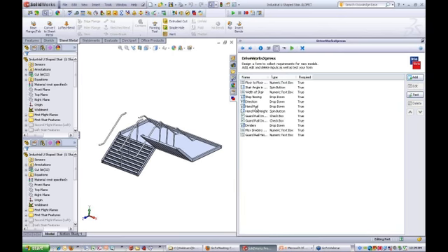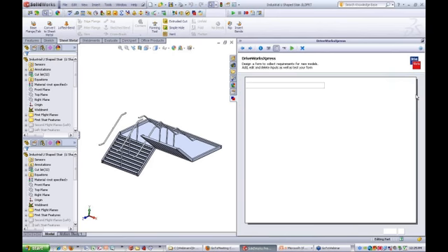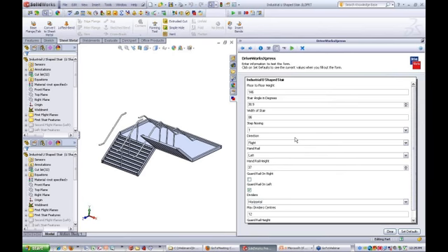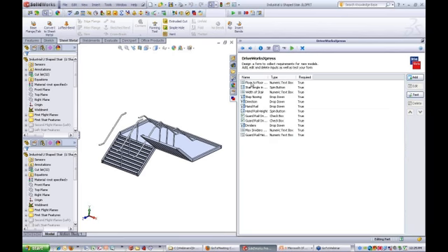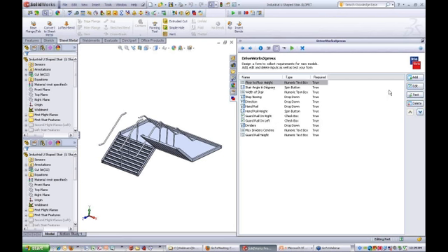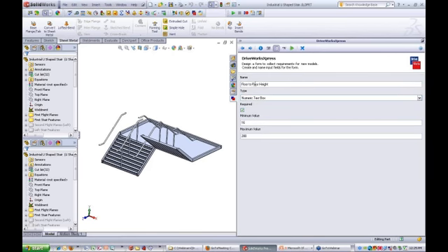Now here's the form that we were filling in before. I'll just run a test mode to show it to you. So there's the form you saw before, and these are the fields that are in there. For example, the floor to floor height is the first field that we entered information into. That was a numeric text box, and it's definitely required. If I just edit that to show it to you, there's the name that was put in. You can define the type of data entry it is, whether it's required, and the minimum and maximum values. Here's where we put our control over the data we can enter.